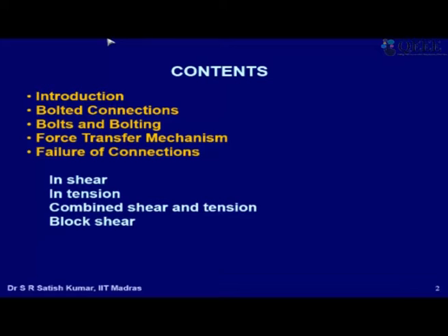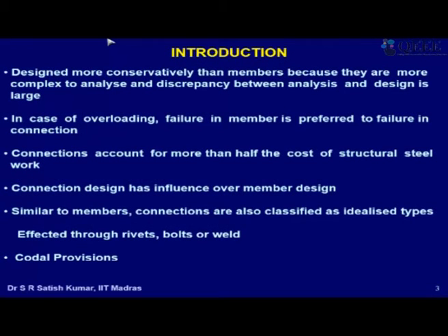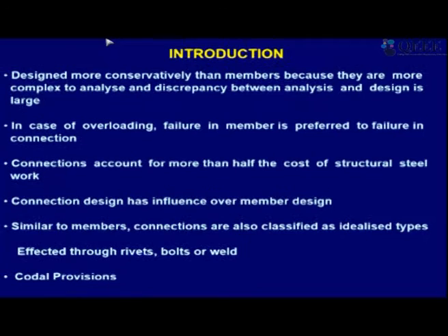Then what are the types of bolts that are available and how do we install the bolts, then force transfer mechanism, failure of connections in shear, tension and combined shear and tension. Block shear we have already covered in tension members, so I just put it as a list that one more possibility is there. Generally connections are designed more conservatively than members because they are more complex to analyze.